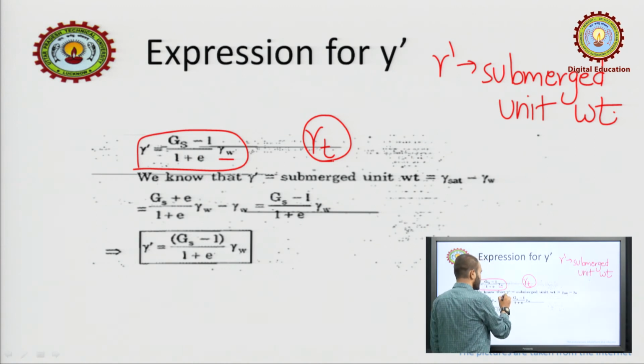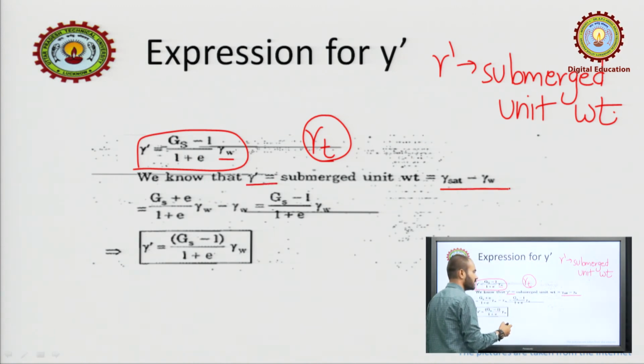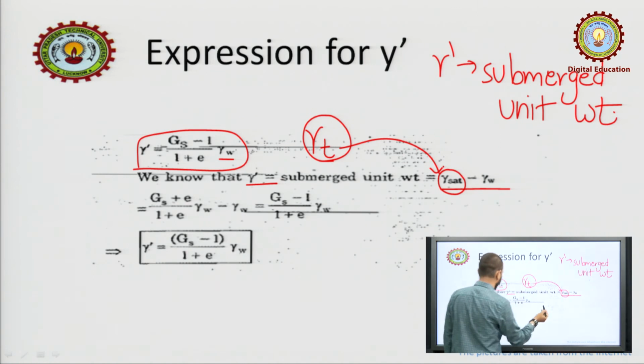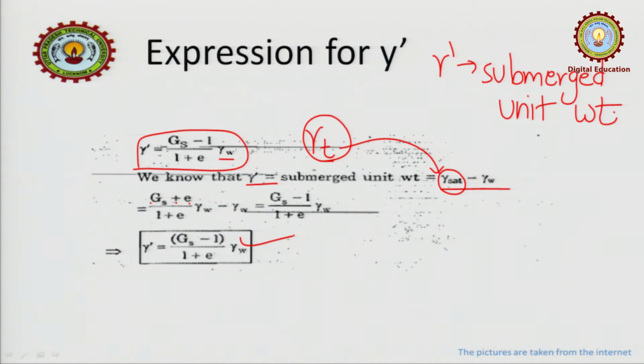How? Submerged unit weight, if you remember, is gamma saturated minus gamma w. I have already explained this to you. Just replace the gamma saturated expression which we obtained from gamma t here and simplify, meaning (Gs plus e) upon (1 plus e) gamma w minus gamma w. Just take the LCM and simplify it to get this, (Gs minus 1) upon (1 plus e) into gamma w. Okay. So, let us move forward.